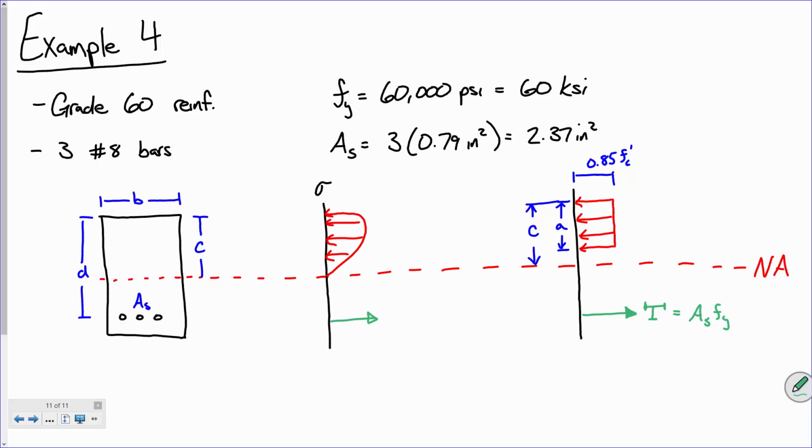Now, I did the easy one. You do the hard one. This compressive stress block, I'm saying that we can idealize that as a compressive force C. I can do a little better than that. What is the compressive force? It's the same deal. We're talking about a stress times an area. I'll ask you the easy one. What is the stress level in this compressive block? How much stress is in that block?